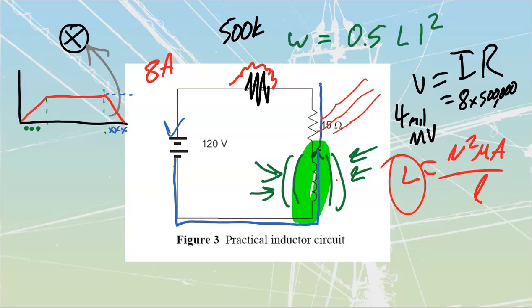We'll use it in some places. Some places we want an arc. Igniters, DSI, direct spark ignition, is a very common thing when we're working with gases. Gas furnaces, gas-driven appliances. Oftentimes we don't want to run a pilot light, but we want to run an arc that is going to collapse.